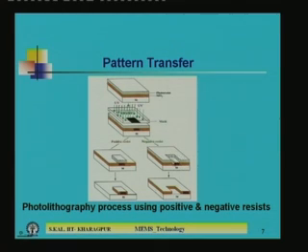So, through the photoresist window you can etch the silicon dioxide only in this portion, as a result of which you get windows on the silicon. Similarly, here the complete silicon dioxide film will be etched, and in the covered region the silicon dioxide will remain. So, in the same structure, if you go for positive or negative resist, you will get a similar kind of pattern after development and etching.